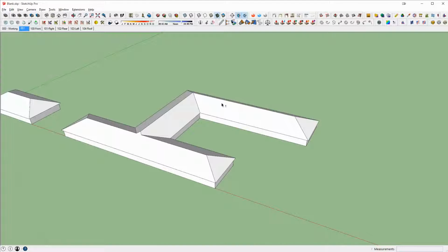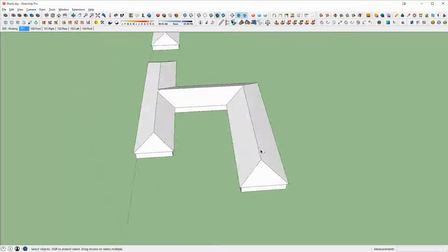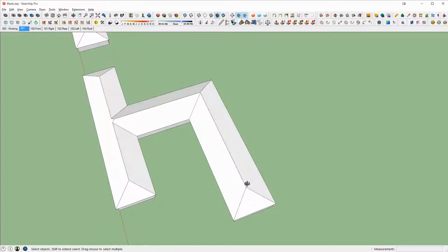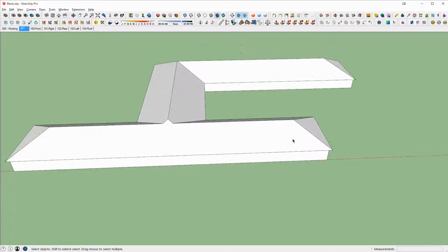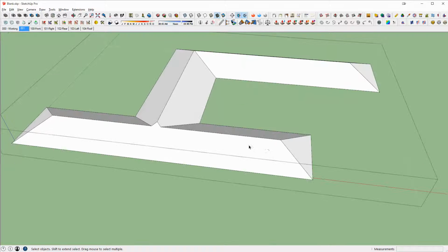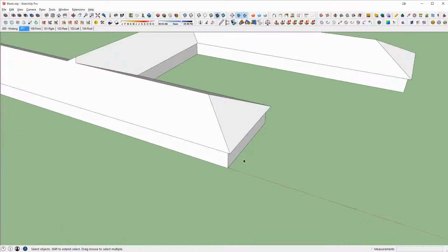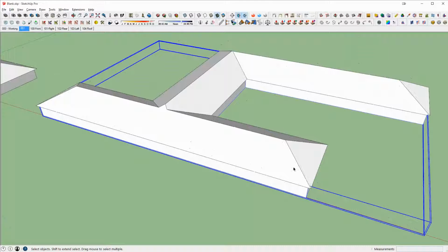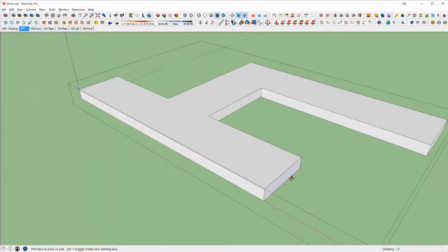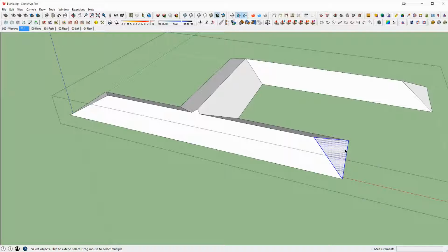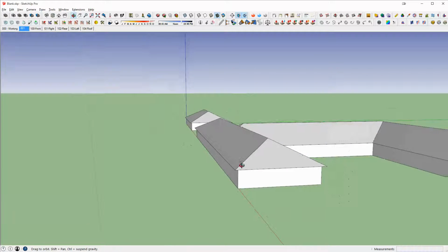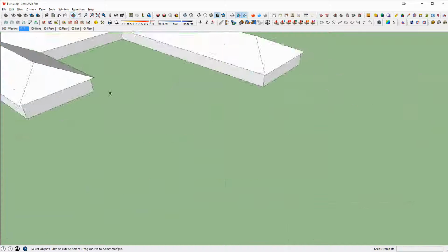And coming back to the solid tools, what could be interesting is, say that we want to edit this roof. First, let's start maybe the house shifts. So we want this house to be pulled in by 20 feet. We can double click this roof, just select this face and move the face in 20 feet. Simple enough. We now adjusted the roof. We're good to go.